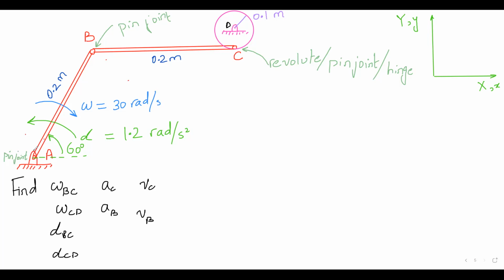Okay. So if you can just write the first equation, why don't you write the equation for us? We really want to start with VB, right? Is it easier to take B with respect to A? Of course. As of now, for sure, we do need to start the problem using point A. And why is that? Because we have alpha and omega there. VB equal to VA. Good.